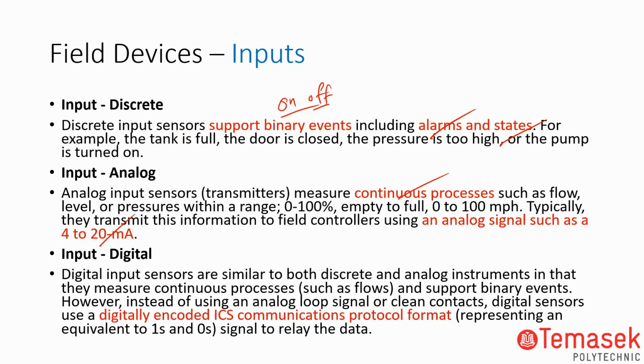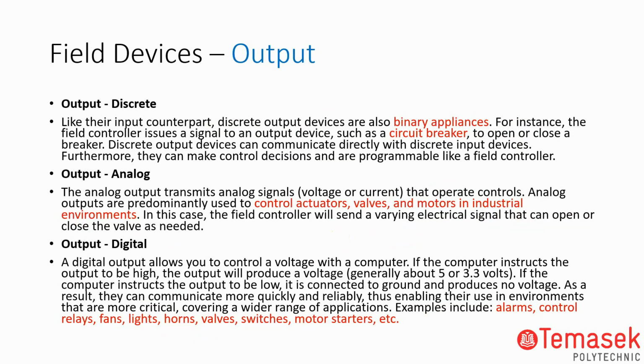Then of course you can change it to something discrete. Finally, I mean digital. At the end of the day, the most important thing is digital, because it needs to be processed, and it needs to be in ones and zeros. Definitely ones and zeros. Of course, a one doesn't mean that it definitely needs to be 5 volts if you talk about today's processors. If you look at the modern computer, to be even more power efficient, logic 1 can be as low as 1.8 volts, and 0 volts. So this is the portion on the data itself.